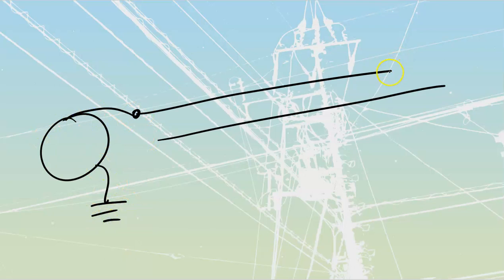What we will do is connect, and we will make sure our conductor itself, so these are my two conductors inside of a 2-conductor cable over there. We won't look at the bond right now. I can connect one end onto my megger over here, and then I'll connect the other end of my megger to ground, and then I will isolate this end so it's not connected to anything, and then I just turn on the megger. What the megger does is it starts to measure, and it starts to look for where the insulation starts to weaken. And then it gives us a reading off of that.